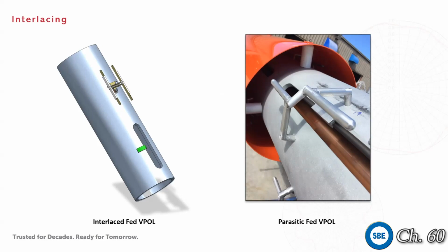Now, if you think back to the history slide previously, you might be thinking, well, perfect, this was back in the 80s, the problem has been solved. And unfortunately, no, it is not. For us, at least it has. We always use these parasitically fed dipoles, but there are some inferior designs that float around that continue to use that sort of interlace fed vertical polarization.